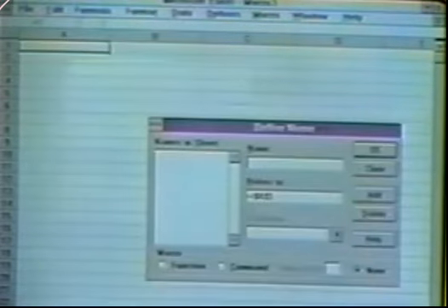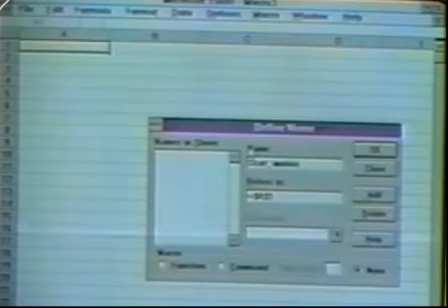We go into Formula and define a name, which we'll name Start Motion. And we want to define this as command. We can now type in the macro definition, and once again, these are Excel-specific macro statements. I'll begin by expanding the column so we can see the full text.